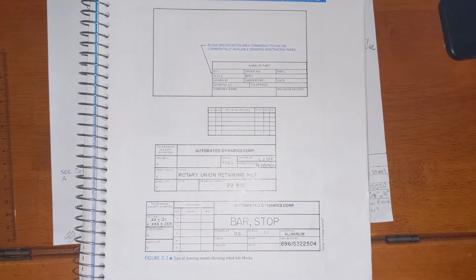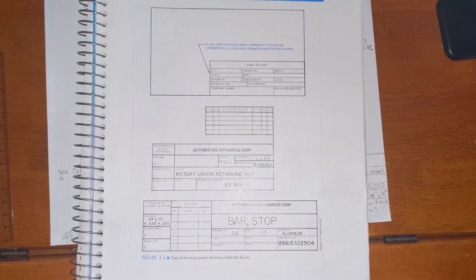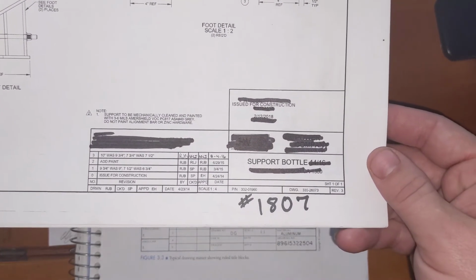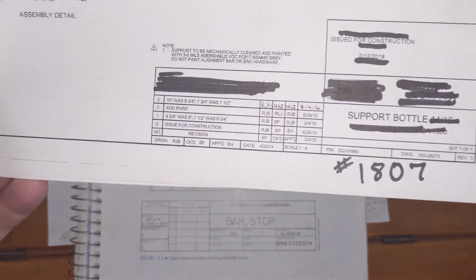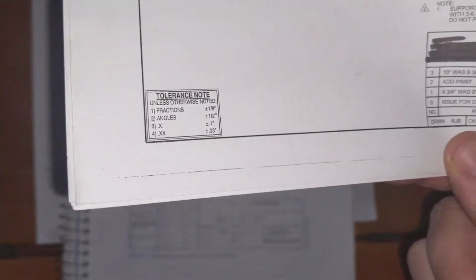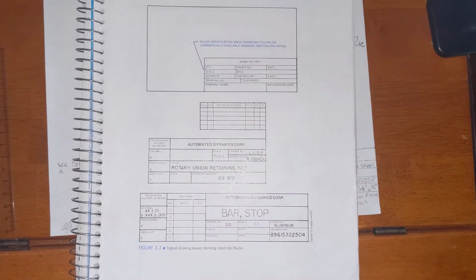And just to show you guys, this isn't just what you'd see in a textbook. I have a drawing I'd like to show you that specifically shows that there are multiple ways to do this. Now, I've crossed out some names because I no longer work for this company. But we can see that we can give a lot of the information. We can see different engineers who've drawn this. We have a revision record over here where we've had different revisions added along the way. And then also, some people will put the tolerance in a special little box. So for all of our dimensions, we have plus or minus 1/8 of an inch. Any angles, plus or minus 1/2 degree, and so on and so forth. So this isn't just what we teach out of the textbook and hope that you'll run into it. This is literally what you're going to run into in the real world.